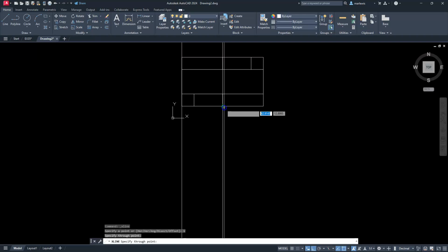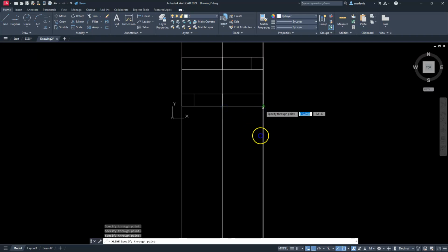Now I'm not gonna pick all of them. That way I don't want to overly confuse my drawing here at the bottom. But I will select these 3 lines. Let's go back to the line command, so just L enter. I want to draw a line going straight across here. Go ahead and hit escape.